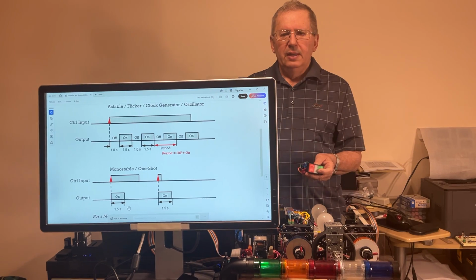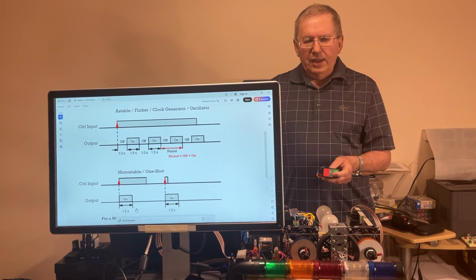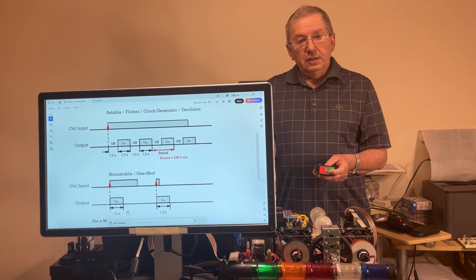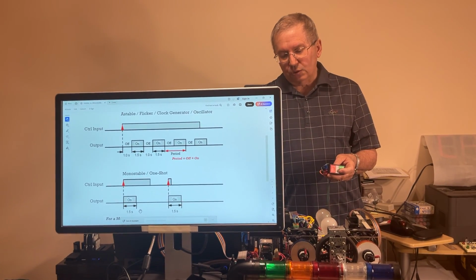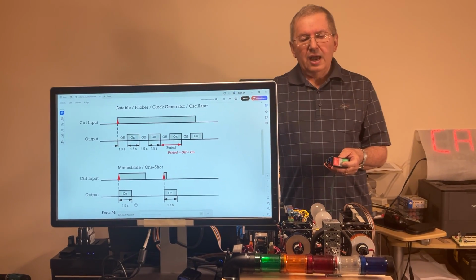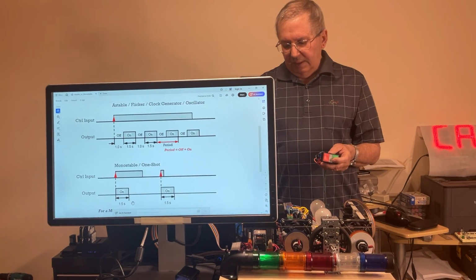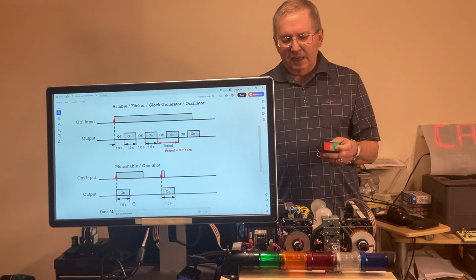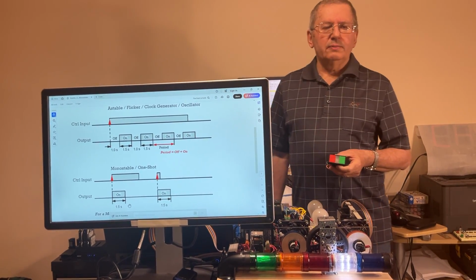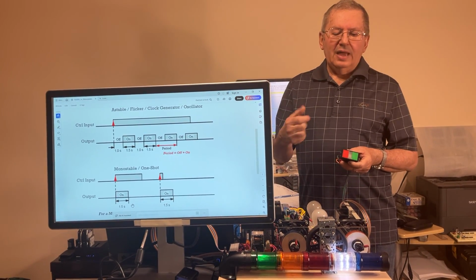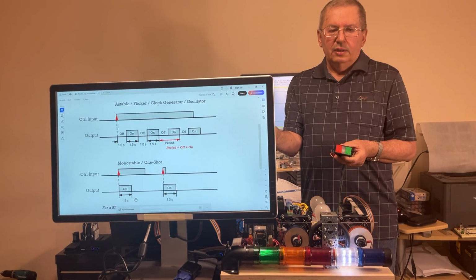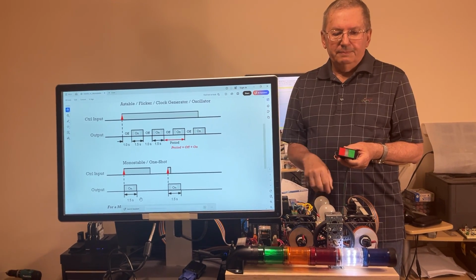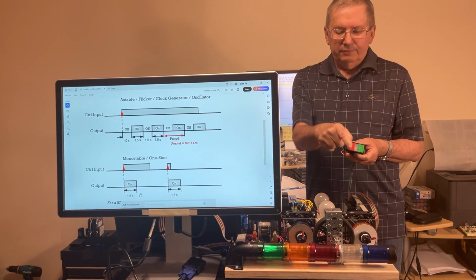It doesn't matter. And I'm giving you 3 examples. So I put in this location, depending on what push button I press on my PLC, one of the 3 values. It can be the 10 seconds, this one here. So now the timer takes its value of 10 seconds from the memory location I stored the 10 seconds in. So in 10 seconds it goes off, see?